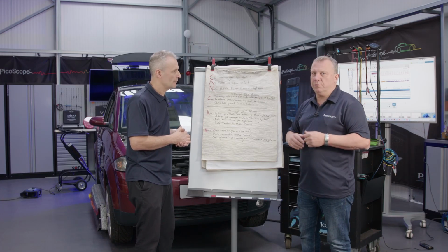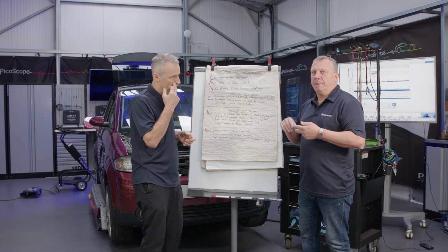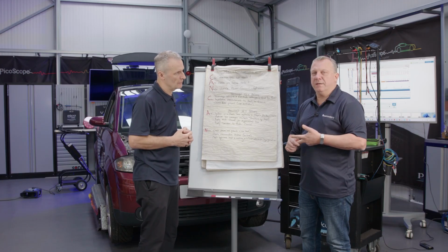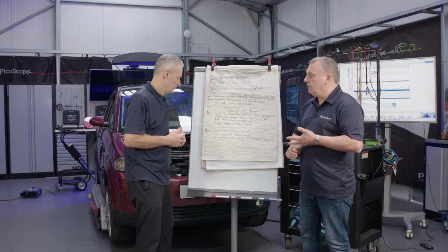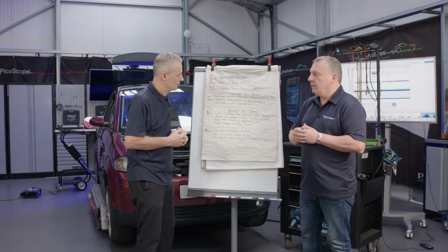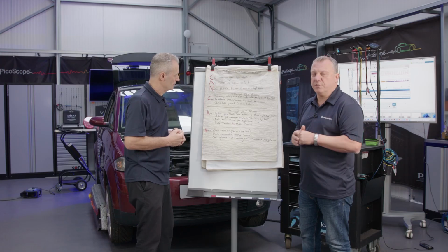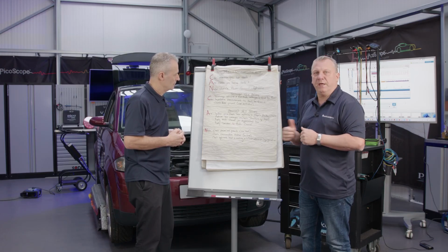You just need to know, you do your just-in-time learning, make sure you know what network you're working on, expect what you inspect, and then do the testing that's applicable to that particular network, following the CAN testing procedure, which is, can messages be sent? Are messages being sent? Are they being sent successfully? And don't forget to check the node.